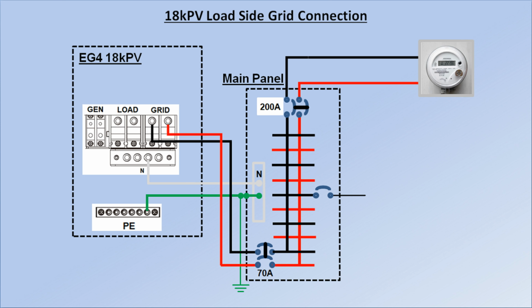Moving on to the bus bars, which is the actual topic of this video. It might be obvious, but these are the bus bars in this diagram. The purpose of this code is to prevent the bus bars and load panels from being overloaded. Too much current passing through the bus bars can cause them to overheat. If the overheating is excessive, the copper or especially aluminum bars can become damaged and fail, possibly even causing a fire. I've seen this happen with aluminum bus bars, which only caused a power failure in the house. It required installing a new main panel to fix it.